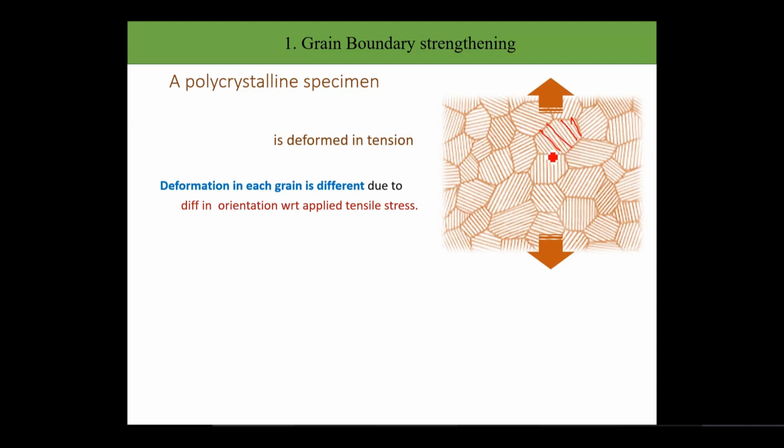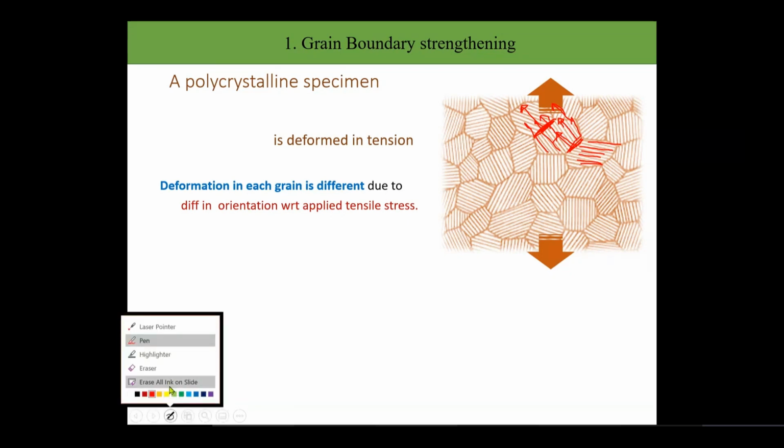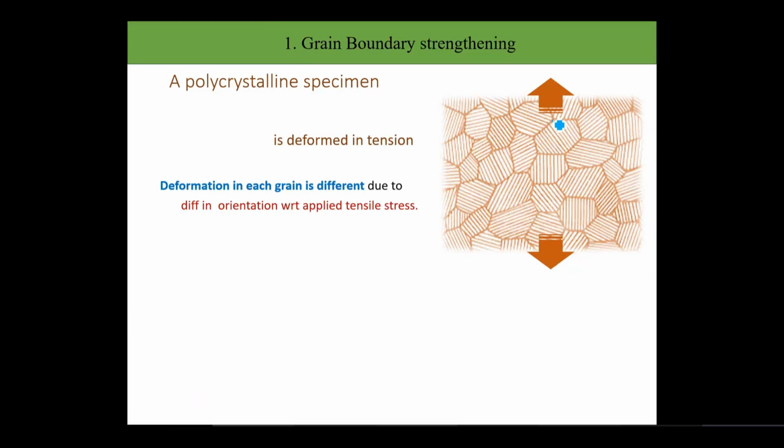Let's say I am assuming this is the direction of deformation. तो ये जो क्रिस्टल है ये ज्यादा मूव कर रहा है इस डायरेक्शन में, तो ये वाली ग्रेन बाउंड्री is moving more and overlapping the other grain, और यहाँ पे डेफॉर्मेशन कम है तो ये वाली ग्रेन बाउंड्री इस डायरेक्शन में कम मूव हुई है. In other words, due to the applied shear stress, this grain boundary has moved more in this direction, whereas this grain boundary would move lesser in this direction.